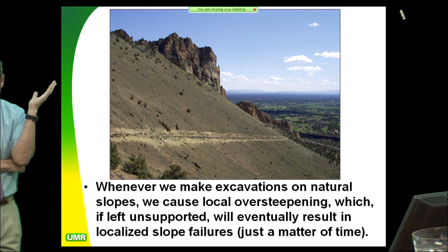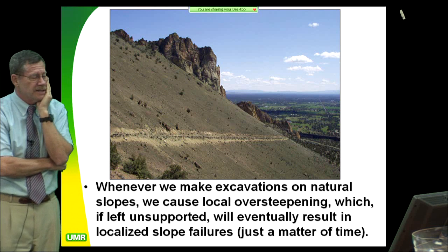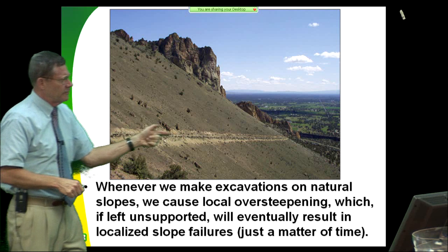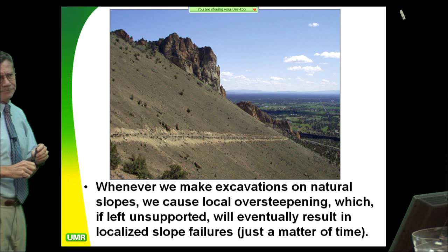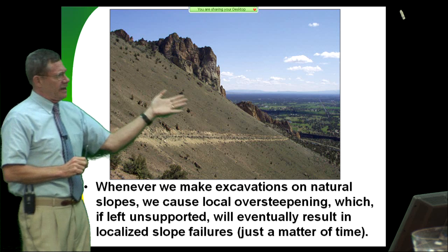What's going on? Erosion. Erosion still going on. Very good. Yes, erosion is still going on. So if I cut a slope in here for my road, what's that going to do? That's going to oversteepen a slope that's right at its phi angle.